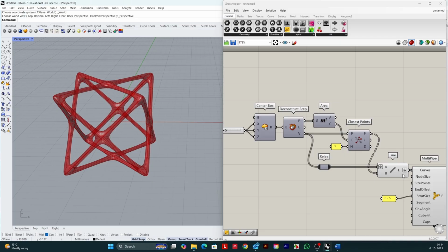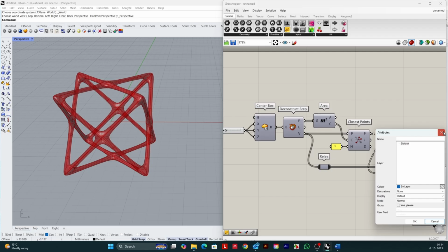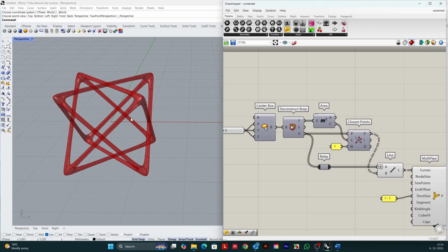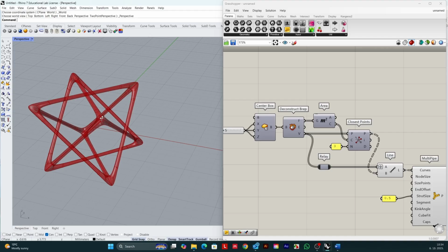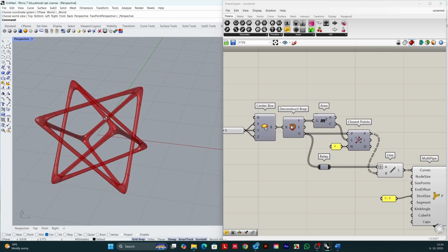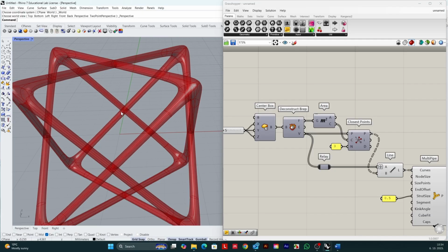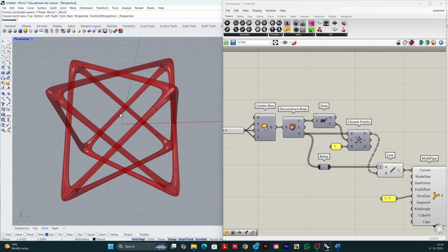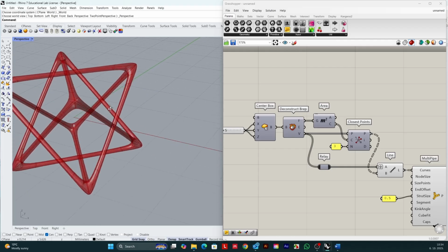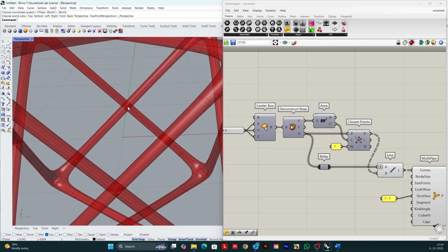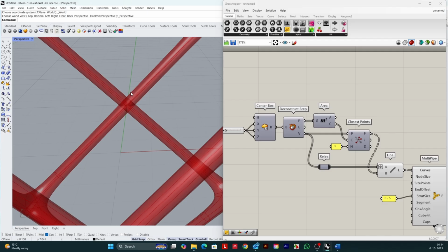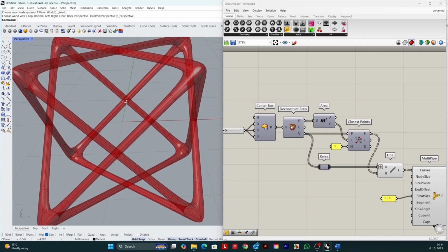If we turn off this flatten option, these places of intersection will lose node creation, and we have a situation where struts pass through the bodies of each other, or cross each other, and in these places we will not have any kind of node.